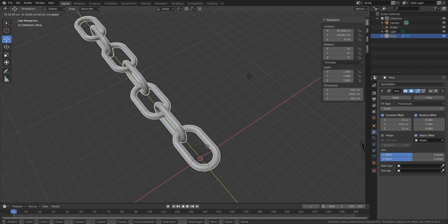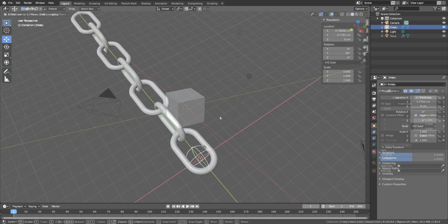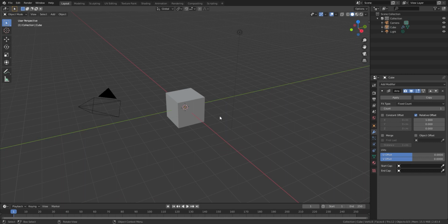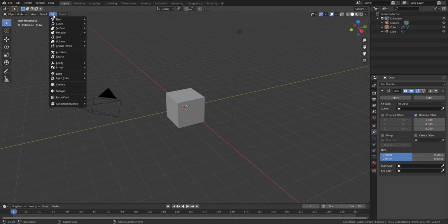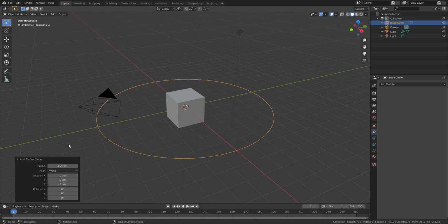So it can be improved, and it's possible to create different formations. Another useful function is that we can do replication along a previously drawn curve. It's called fit curve. It's called fit because it affects the full length. The curve may be closed or opened. Now we add a closed circle. It cannot be visible at the moment, so let's increase the size of it.